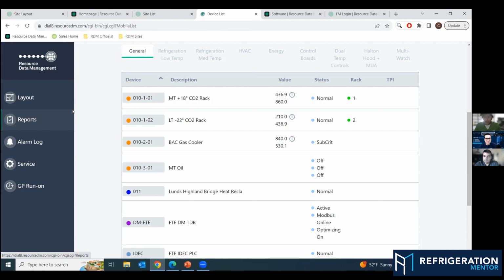Well, yeah, you kind of got to look at these certain things, and there are settings in the controller that can cause that 100%. Here in a minute, we'll go over that, and we can kind of walk you through some of the settings to look at. I can say foremost, Trevor, closed door frozen food cases. I have noticed that EEV and EEV/T settings on our controller, frozen door glass, closed door, I like to see EEV settings on that. And here's why.